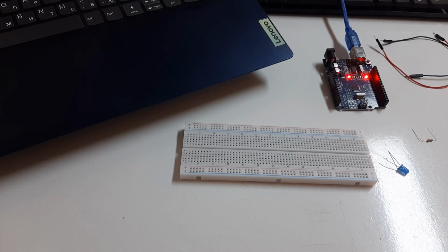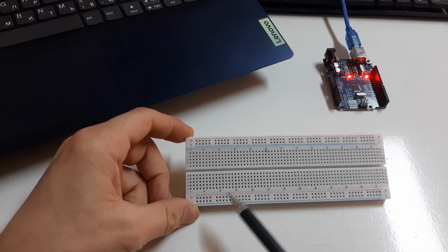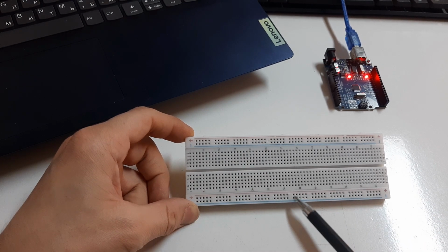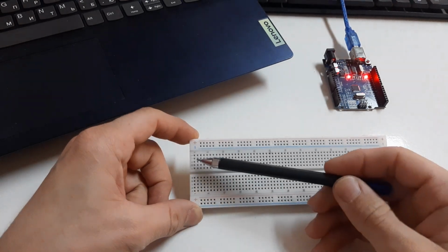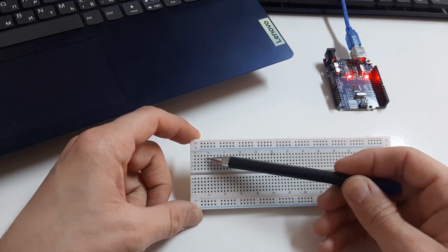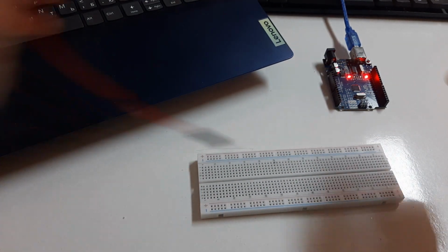Here I will use a breadboard so that we understand the logic. Think of the horizontal, red and green lines at the top and bottom of the breadboard as 2 separate straight wires. We usually connect a positive to red and a negative to green. The vertical holes in the center are divided into groups of 5. Each 5 holes is a line. The middle part is insulated and separates the upper and lower parts.